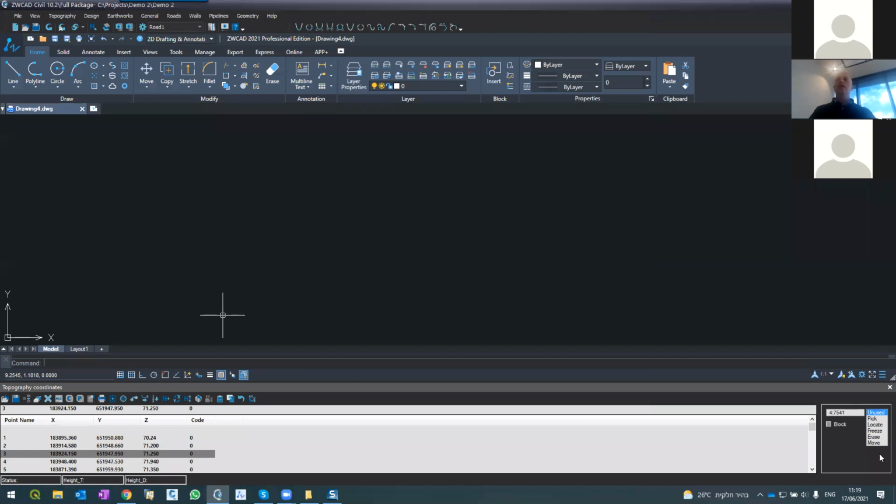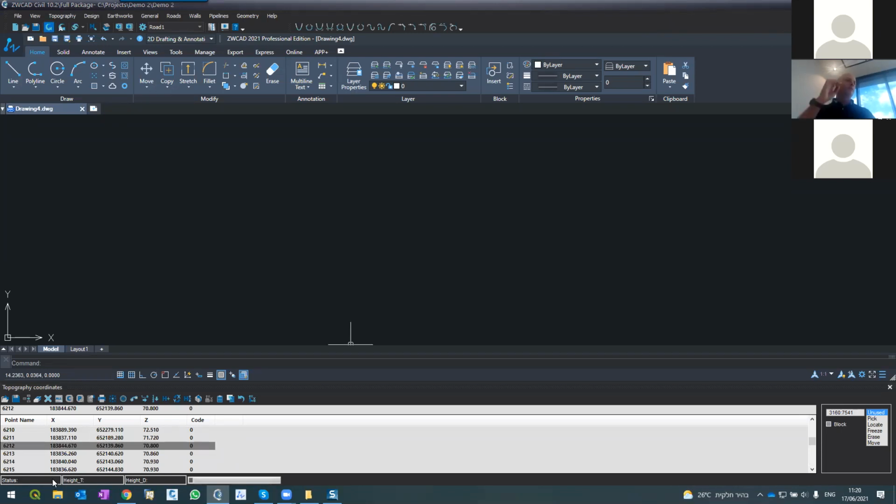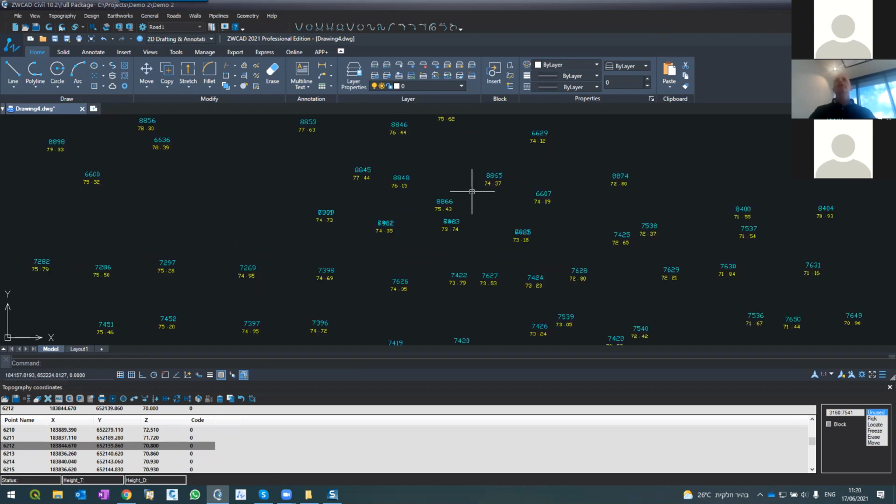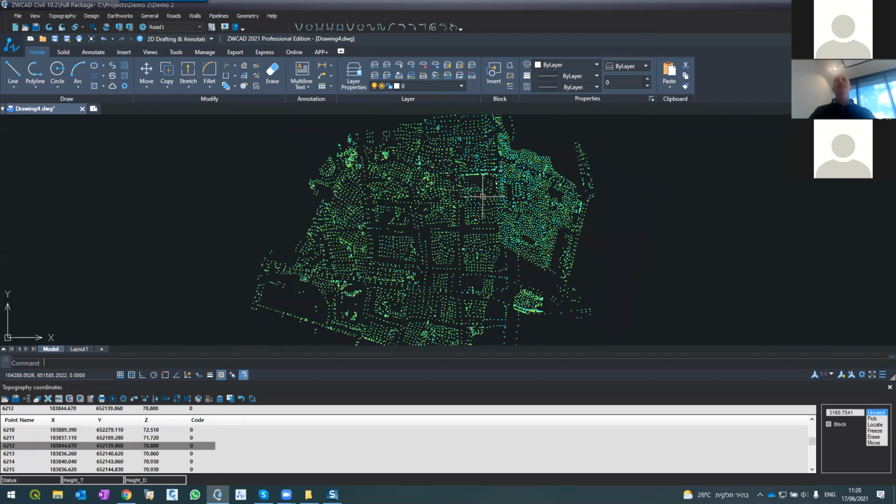And you see there's a long list of coordinates here below, which I have from my GPS, total station, or whatever. If I refresh now, the software will analyze all the coordinates and create the layer out of it, like it did before. So you can see the scroll bar here. It's a little bit longer. Of course, it's not only 4 or 5 points, thousands of points here. And I'm getting the same result the way I did before, but now for a much bigger area.